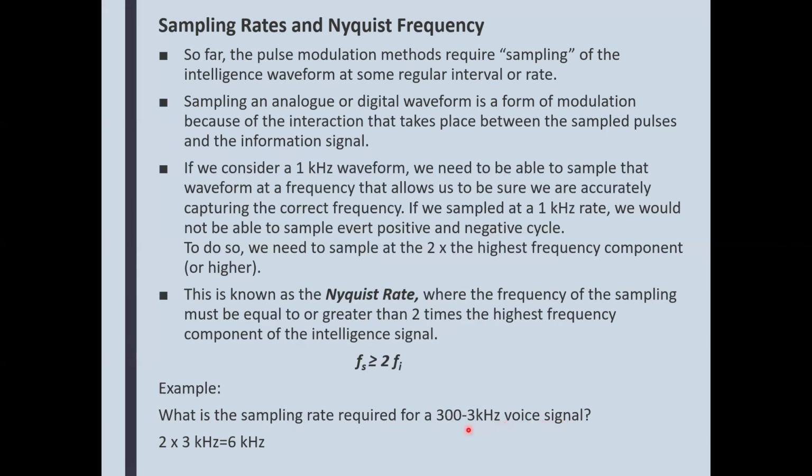Well, the highest frequency that we care about transmitting for voice is 3 kilohertz, and twice that will be 6 kilohertz. So you need to sample a voice signal with at least 6 kilohertz samples, and then you can comfortably understand what somebody is saying.